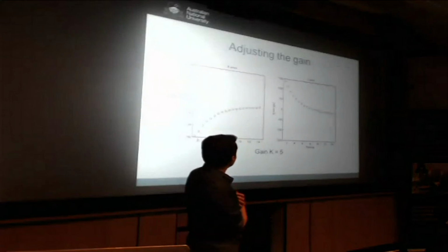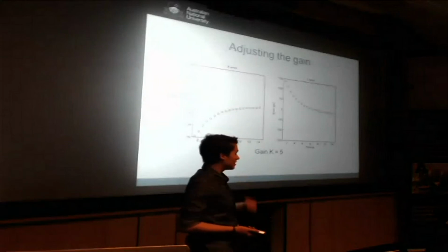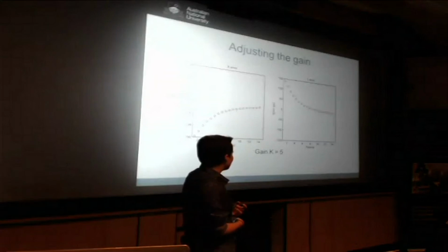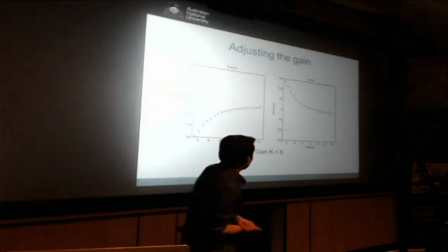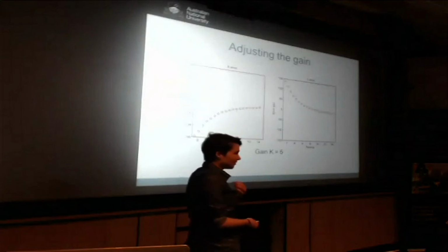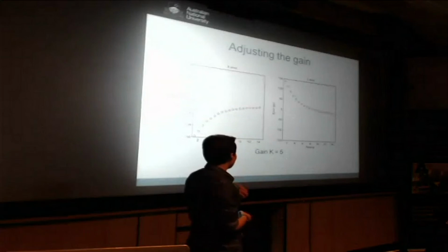So these are some plots of the x and y coordinates of the centroid of the laser beam as a function of time with different gains. Also, by the way, this gain is not normalized. So with a relatively low gain of 5, we see no overshoot in the response, and also it's very sluggish, and it takes almost 15 seconds for the beam to be placed back to the center. This is clearly not ideal.